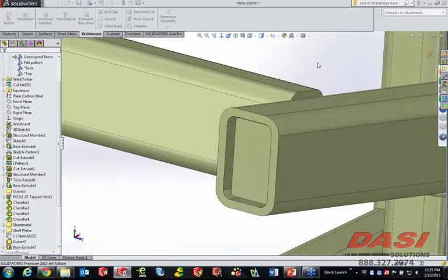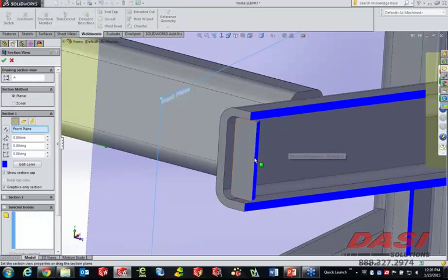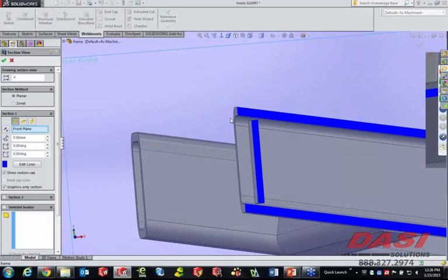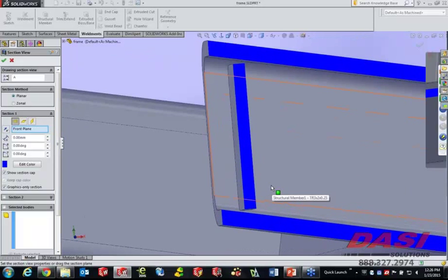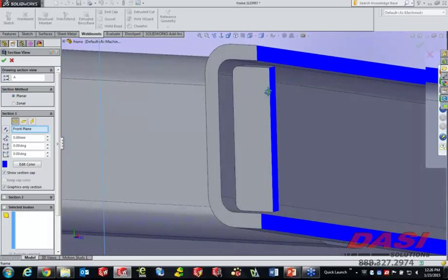When we say OK to this, what I found most interesting here is that we don't create an end cap that's actually going to take 3-axis CNC to create. Somebody was thinking about this. We make an end cap, and even though it's perpendicular to the end face and not perpendicular to the actual body because of the angled cut, we create an end cap which is actually perpendicular geometry so that it can be simply lasered out or single end milled out and then placed in and held and welded. We're not making a bevel on this face to make the end cap one of the more complex parts of this assembly.